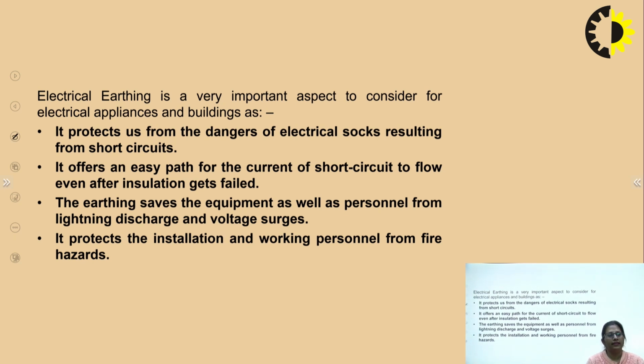It offers an easy path for the short circuit current to flow even after the insulation has failed. Earthing saves the equipment as well as the working personnel from lightning discharge and voltage surges. It protects the installation and the working personnel from fire hazards. These are certain important aspects of earthing.